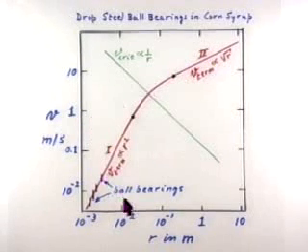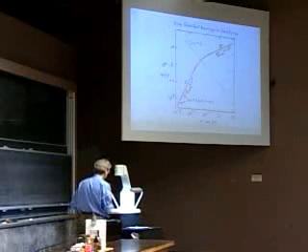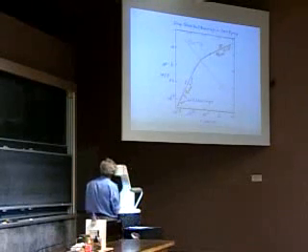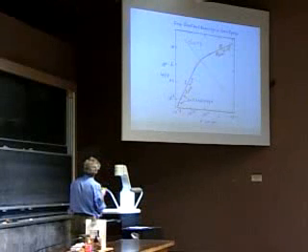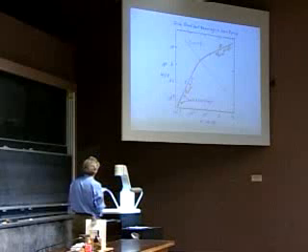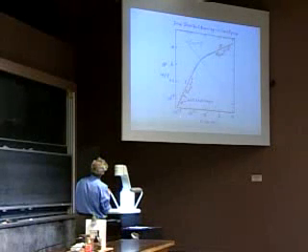Our ball bearings are all here. And so we are exclusively operating in regime 1, where the viscous term dominates. Now you could say, well, what is the meaning of this critical speed here, if they never reach that speed anyhow? Well, this critical speed for a small ball bearing would be some 100 meters per second. That's about 200 miles per hour.